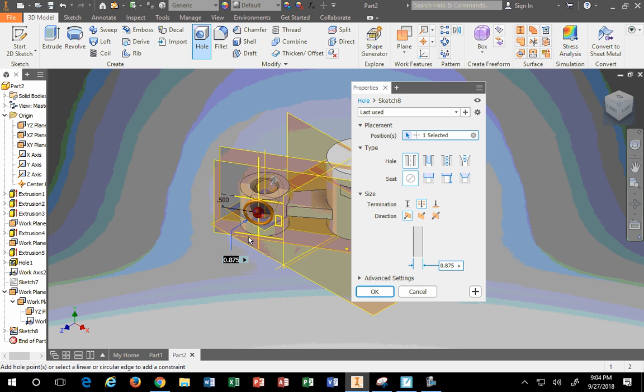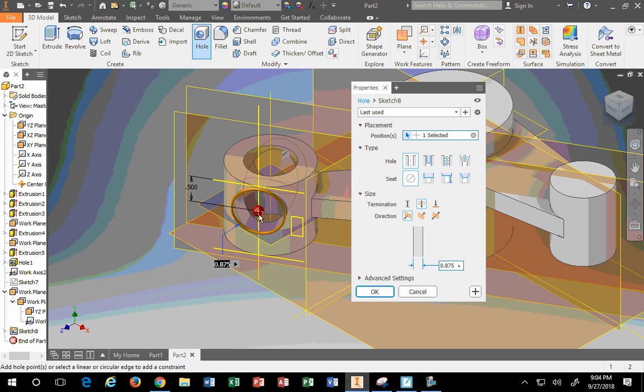Again, this is only one method of building this. I actually built this thing multiple ways in the past. So you just play with it. I want you to play with it. But this is another way to use planes. It's my opportunity to show you the other method of planes. The diameter of this hole is 3/8 of an inch. So I'm going to change this to 0.375.